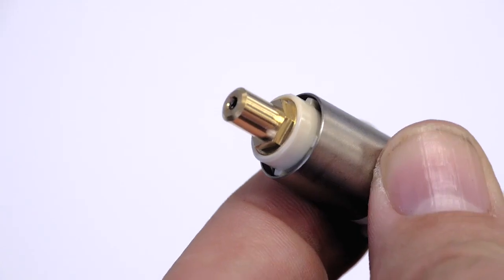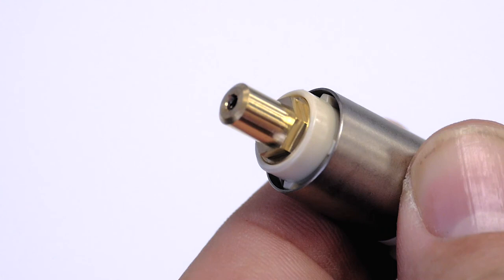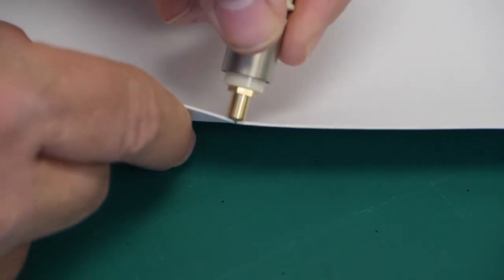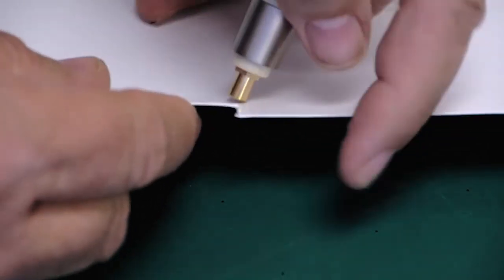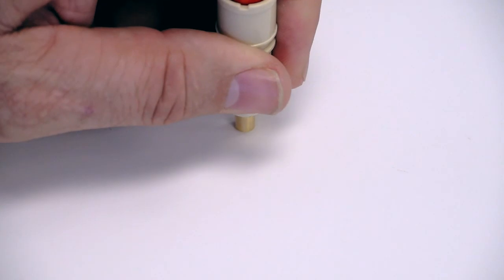Extend the blade so that it's extended to the thickness of the media. This may seem to be a daunting task, but it's not really. Place it next to the media you plan to cut. This should give a general idea of how far to extend the blade. Test the length further by test cutting a piece of material you plan to use.